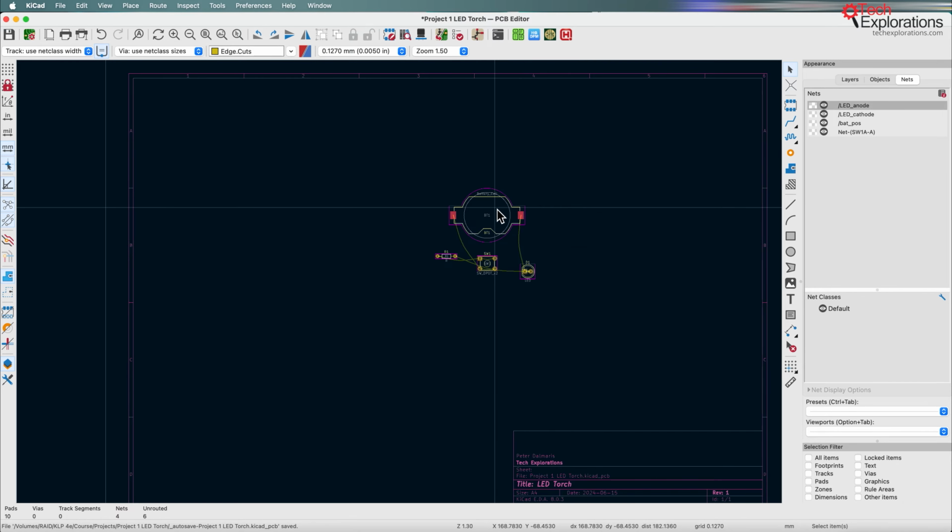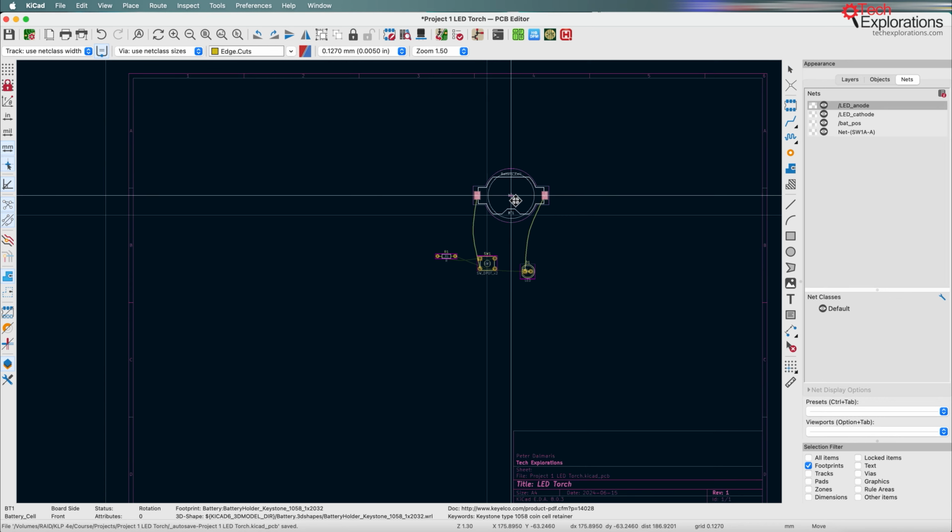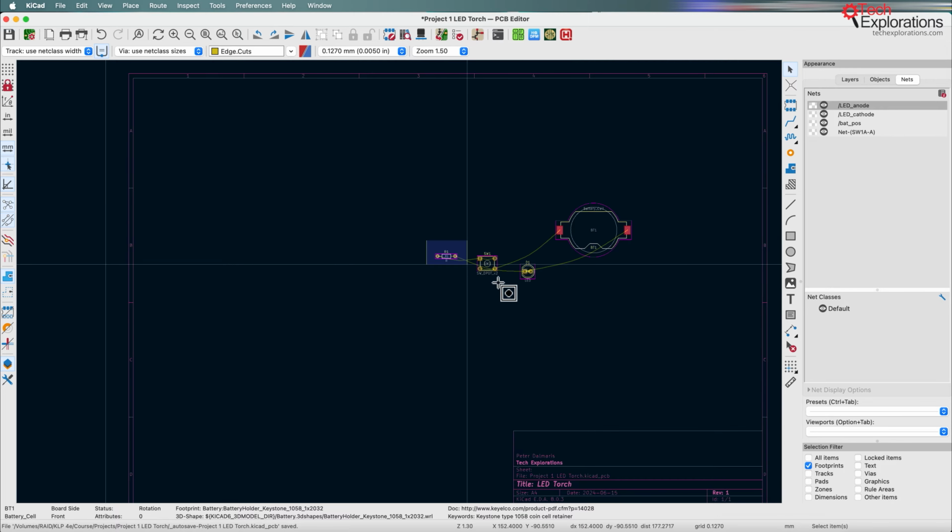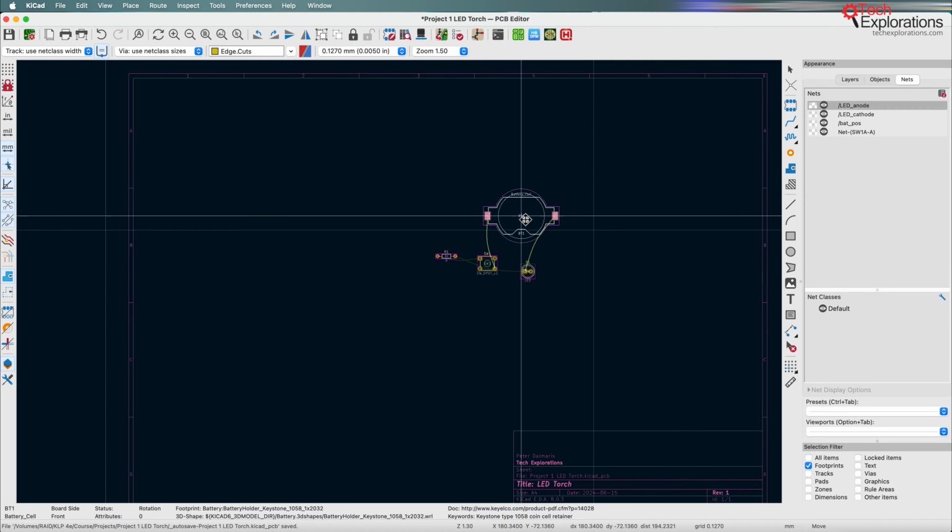Then, what's the biggest component of the board? In this case, I've got a comparatively large footprint for the battery. You can see how much larger this is compared to everything else. So this essentially dictates how wide, at least, the outline for this PCB will be. And then there's also the question of how I will attach the board to an enclosure.